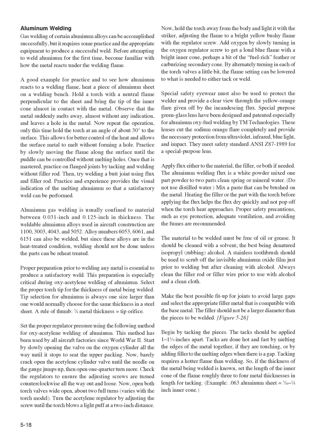Once that is mastered, practice on flange joints by tacking and welding without filler rod. Then, try welding a butt joint using flux and filler rod. Practice and experience provides the visual indication of the melting aluminum so that a satisfactory weld can be performed.